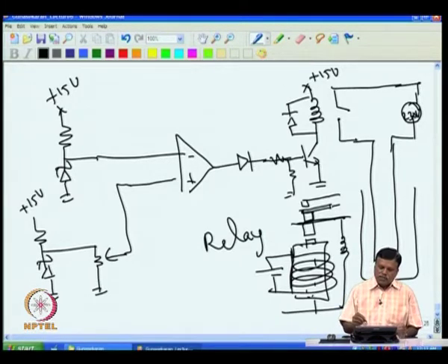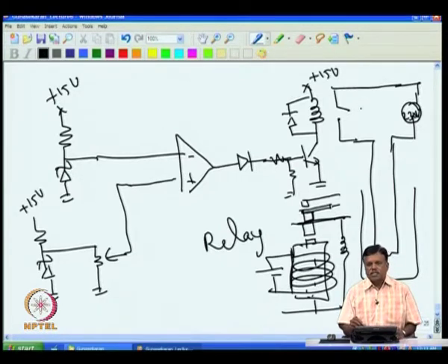Normally we do not try to switch on more than 10 times a second. Also, when you switch on and off every time, you will see a spark coming here, and the contact actually goes off every time you switch on and off, and it also radiates noise outside to the space. So, a relay has the drawback that after several thousand operations you will find the contact here is not good.